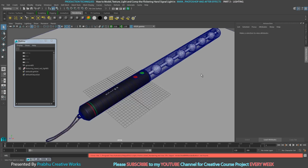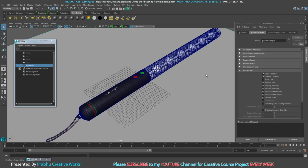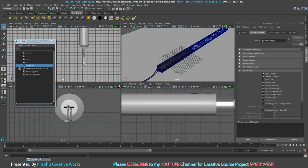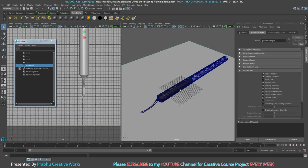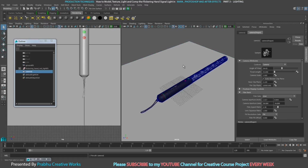So I will click the spacebar to split my 4 views. I drag this one to get two views. One is perspective, another is camera view. So I will split this view, click this button. Go to rendering and click create camera, press R and scale your camera, so it will automatically place in our scene. So go to panels over here,